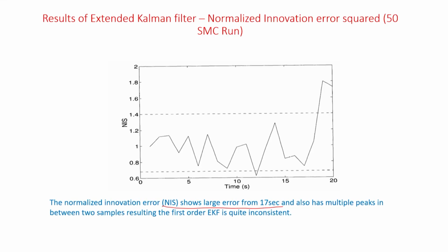So that is why the extended Kalman filter suffers in such cases. But if you take the radar tracking problem that I showed previously, you have range and you have an azimuth angle. So the system is very observable, and you do not need anything else. There are many types of bearing angle only tracking problems, not only this one. In those, EKF is inferior. Well, it won't diverge, but it will definitely be inferior compared to other approaches.